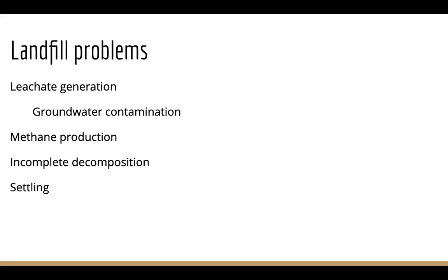Settling, so this is where as waste does decompose, as it does break down, it compacts and it settles. And that can be a problem because if you have a capped landfill and you have decomposition happening, yeah, maybe that's good because then your waste is being reduced by that decomposition, but then the landfill can actually collapse, and that can cause structural problems in the landfill, and then stuff can escape, and leachate can escape, and that would be problematic.